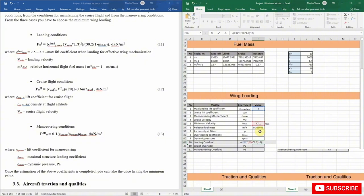Then I will close this whole bracket and divide it by bracket 30.2, multiplied by bracket 1 minus the relative fuel mass at the cruise level, and then two brackets, and we're ready. So we're getting 588 for the loading coefficient, which has the dimension of daN per meter squared. Since we have this one, now we can move on.